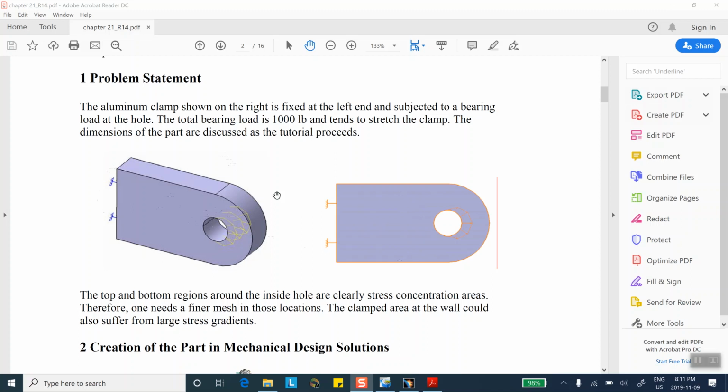It measures an entity, which in the case of Catia is the strain energy density. When the total strain energy reaches a threshold value and doesn't change very much from that point on, to within some specified percentage, the software stops refining. So let me go ahead and model this problem.